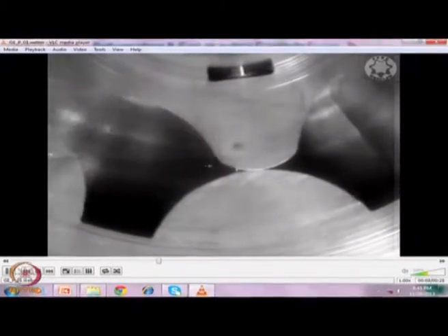You can see this once again. Looking at the bubbles means that at the critical contact there is a gap. Critical contact means when it is separating the high pressure zone from the low pressure zone, and this is momentary. Theoretically it matches my calculations, whereas those who have conducted such experiments have not yet calculated such things, they are only experimentally observing.